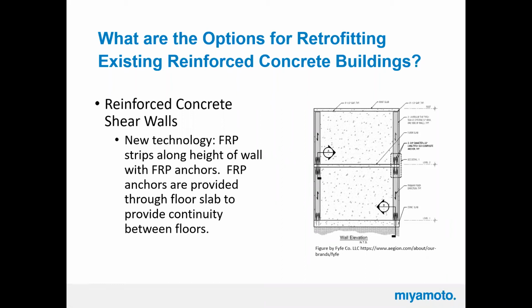Hey, Jeff, this is Pete. Yes, sir. I don't know if we can do that for flexure. I don't know if Wayne can chime in, but ours was basically to meet prescriptive requirements for the city of San Diego, not knowing how to use ASCE 41, but I thought we could only use it for shear, not for flexure, because it's not ductile, it's force controlled, and you have to look at it differently. Yeah, I'm sure there are different provisions in different jurisdictions.